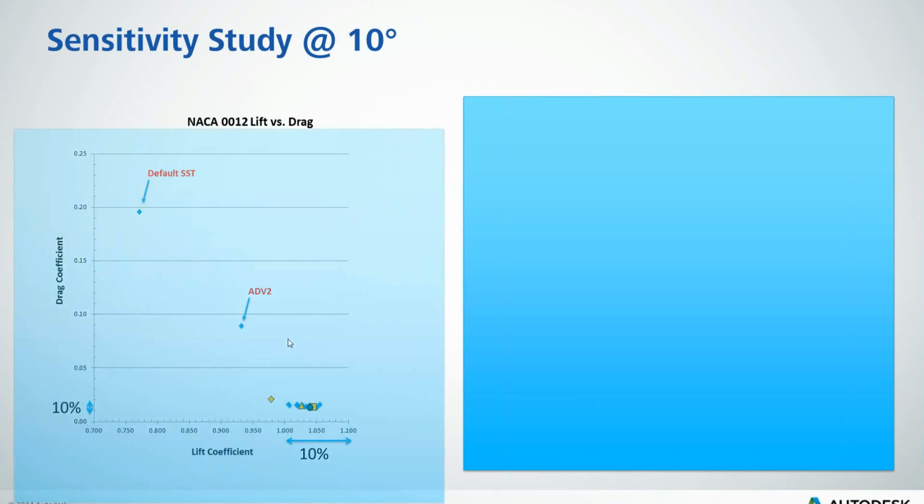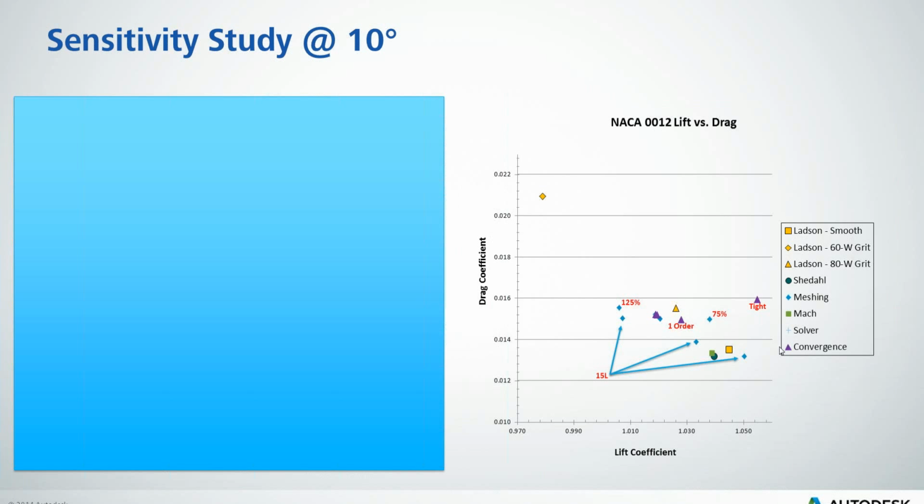Okay. Convergence. This is the one that I found most interesting myself. When we talk about convergence, you're thinking of that window with the auto convergence assessment tool within Simulation CFD. And it starts off with default. You know where default is? If you look in that previous graph on the left-hand side, it's off the plot. It is just way, way out. It's not anywhere close to convergence. Okay. When we look at tight, it starts to get pretty close. It's probably a pretty reasonable place to run your model out, but it really is not fully converged yet.